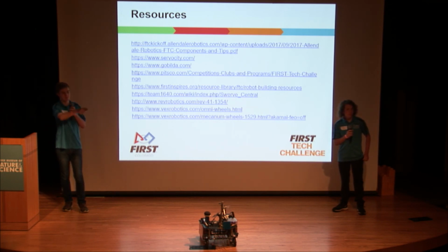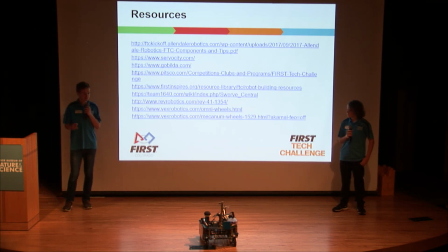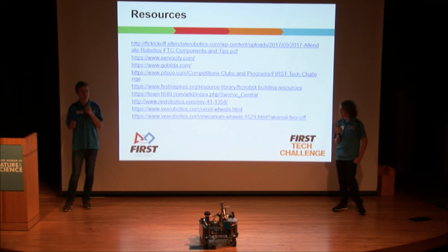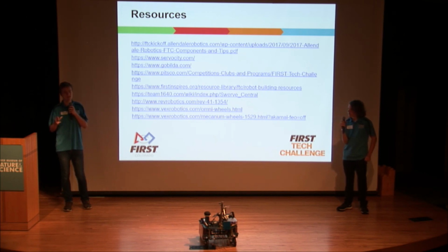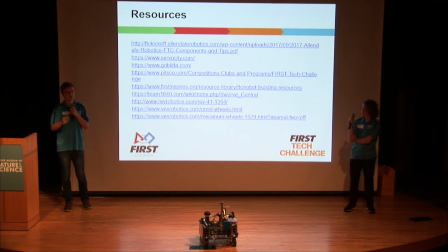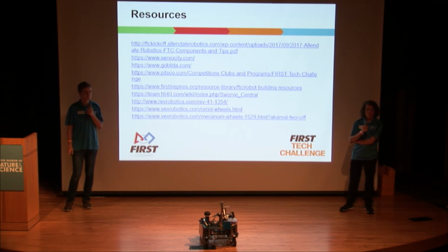What is the advantage of Omni wheels over traction wheels? Omni wheels reduce traction, which is very helpful when you're turning. For example, if you had a tank drive that had a traction wheel in every corner, it'd be very difficult on your motors to turn it by powering one side over the other. Omni wheels allow for a much tighter turning radius and a lot of strain relieved from your robot. So generally, a good balance of the two is a good way to go if you have more than 4 wheels.